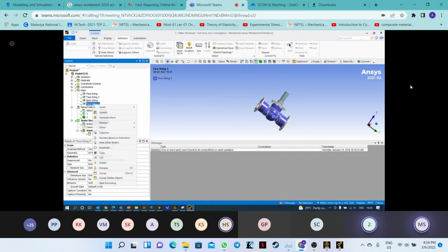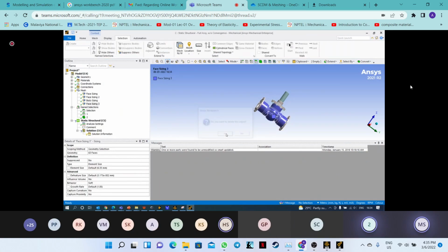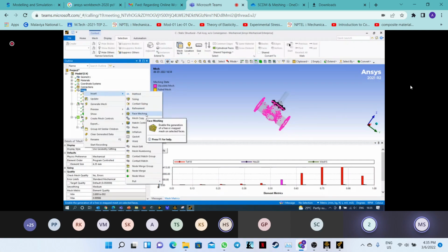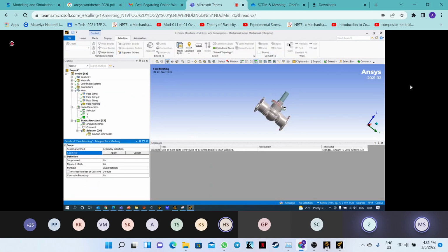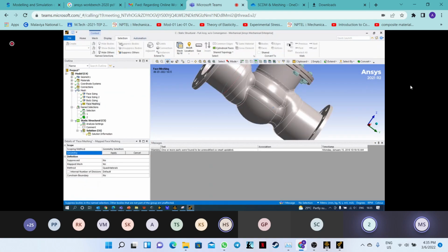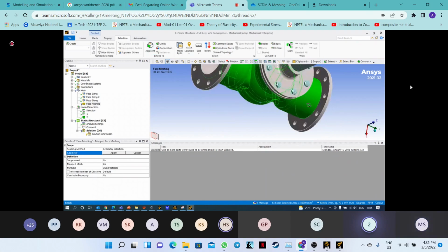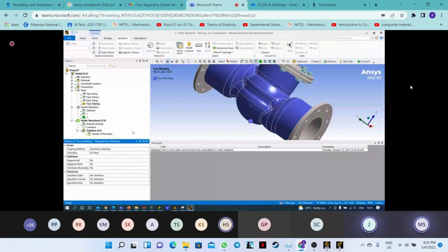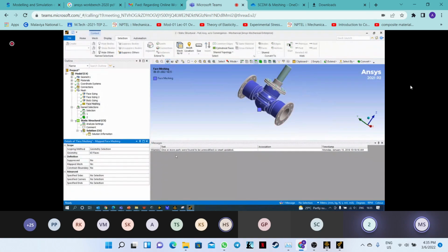So let's just switch to that. That will be the suitable one to show you, because we have not used face map meshing, right? So go with face meshing and just select one of the surfaces. Okay, and check whichever is left out here. Basically this control is going to give the mapping to your surface, so that elements are proper. There are certain advanced settings available, but you mostly don't have to work much on that.